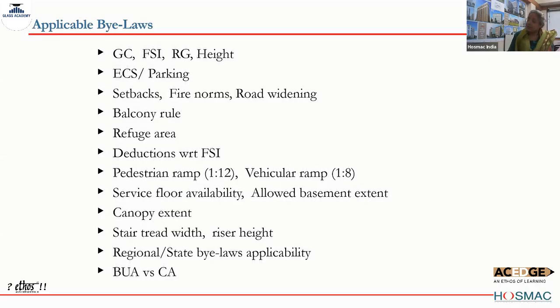And there can be a surprise sometimes if we get a site, a full site, let us say 2 acres, but along the way there is already a master plan where the road widening, the city road which abuts the site is going to take a good 6 meters of the plot because the government has decided for road widening, which means that your functional plot has lessened.